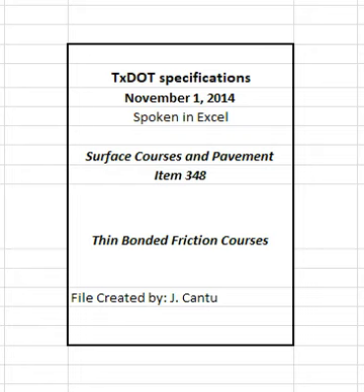1. After standing undisturbed for 24 hours, the surface must be smooth, must not exhibit a white or milky colored substance, and must be a homogeneous color throughout. 2. May be required by the engineer only when the emulsion cannot be easily applied in the field. 3. The temperature on the lower thermometer should be brought slowly to 350 degrees Fahrenheit plus or minus 10 degrees Fahrenheit and maintained at this temperature for 20 minutes. The total distillation should be complete in 60 plus or minus 5 minutes from the first application of heat.